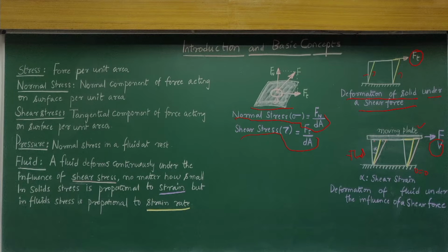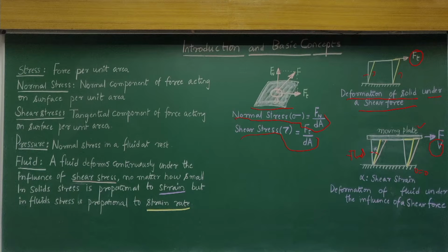Because of that, the fluid element presented here will undergo shear deformations. But as we keep applying the shear force, the shear strain keeps increasing and increasing. Even if you release this force, the fluid will not come back to the original position. So here we talk not about the shear strain, but the shear strain rate, how the shear strain changes with respect to time.